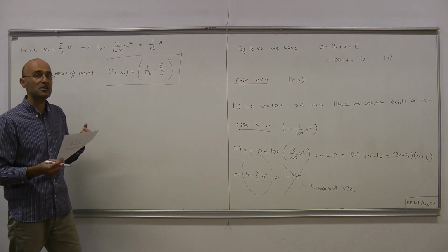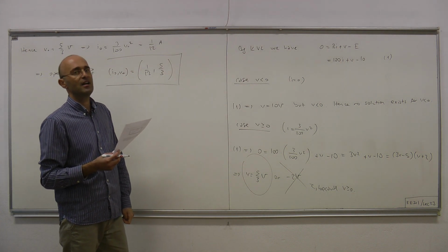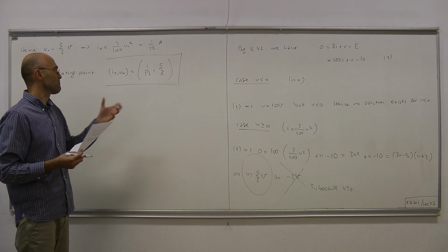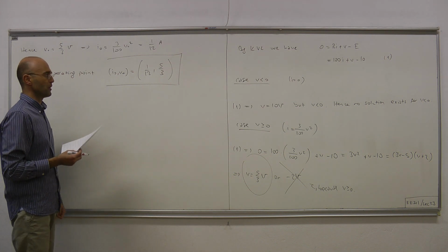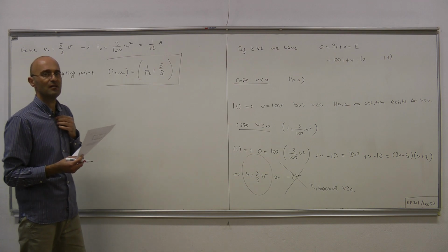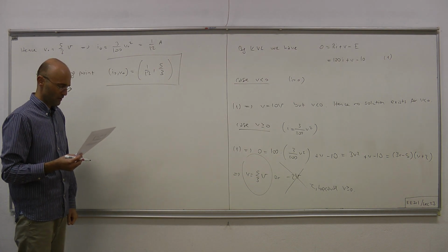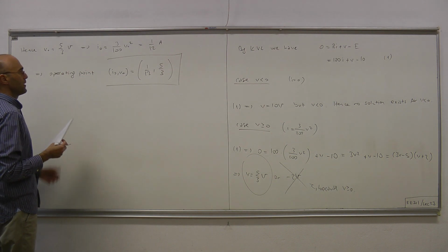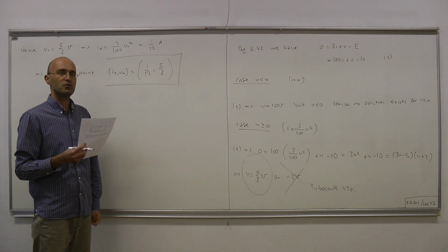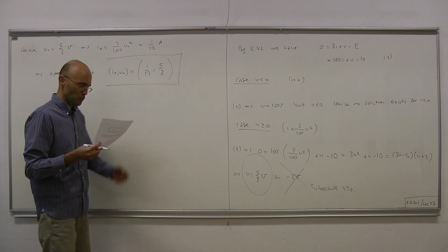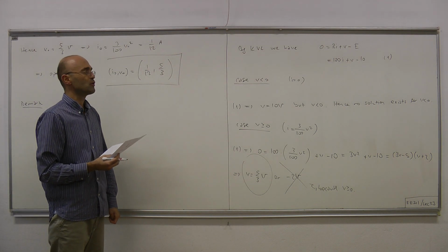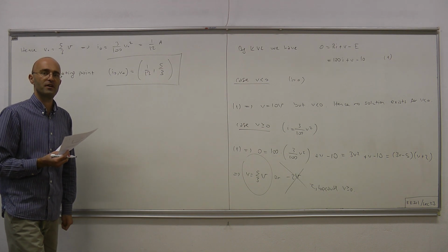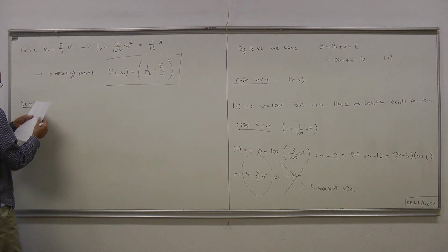And whenever that's the case, it can always be represented by its Thevenin equivalent. And once that linear one port is replaced by its Thevenin equivalent circuit, we have the topology that we work with. Okay. And also, we can use the substitution theorem to deal with the more general situation. So let's quickly remember the substitution theorem, and we will apply it together with the Thevenin equivalent circuit method to solve a more general problem.